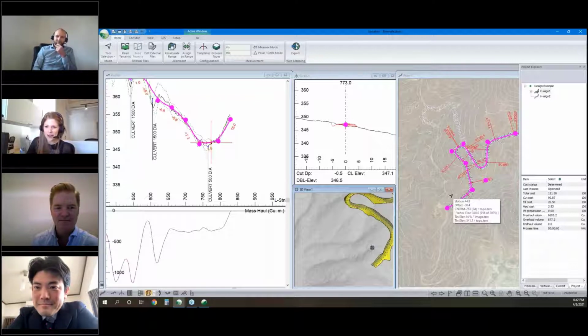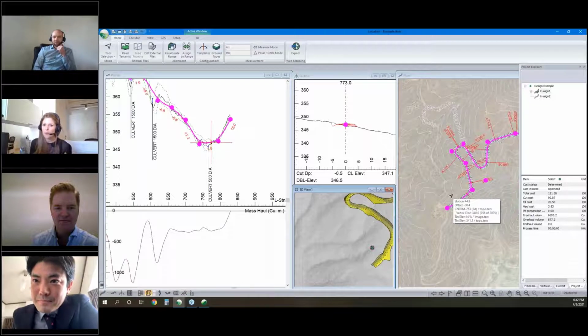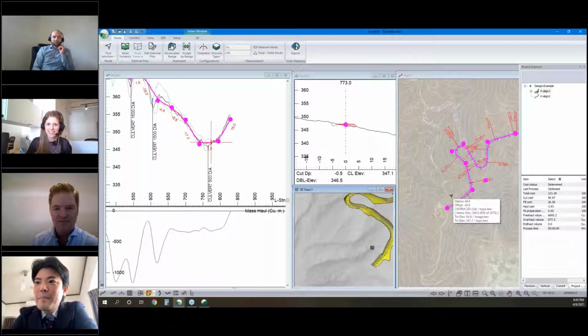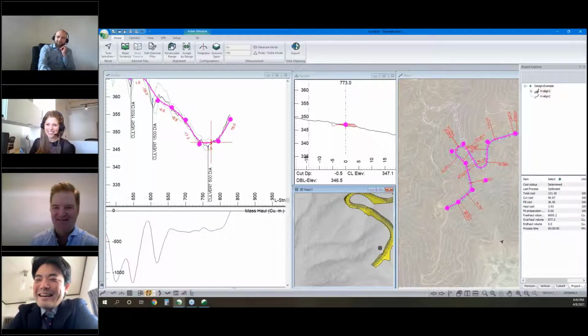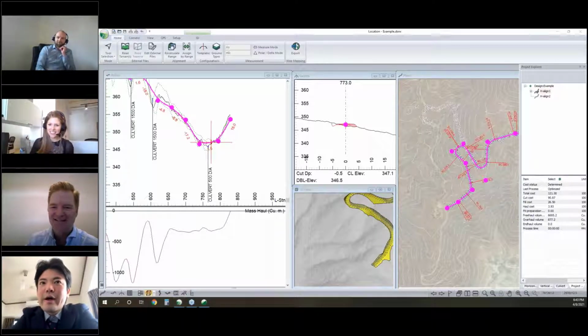This question is for Tepe. It says, I missed a couple minutes at the beginning of the webinar. What was the horizontal and vertical accuracy? Do you mind repeating it? And you are muted. Sorry again. It's a 1 meter RMSE with ground control point and 2 meter without ground control point.